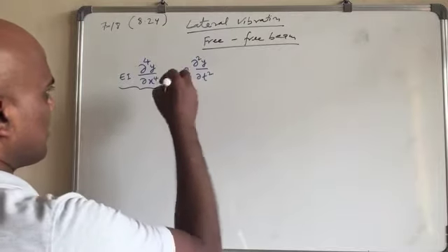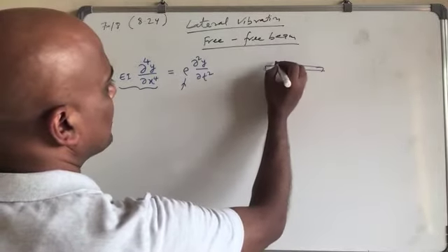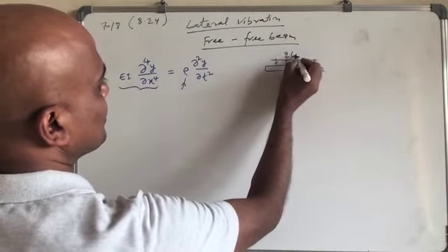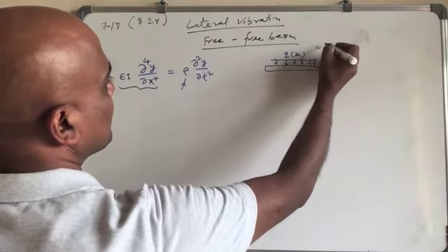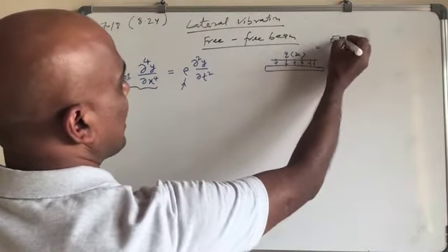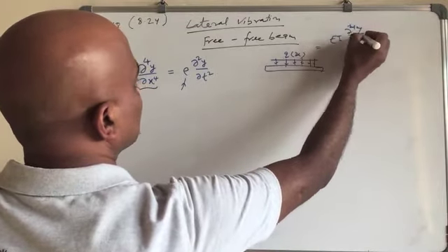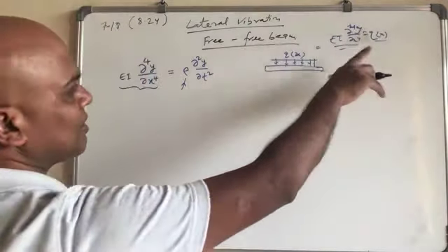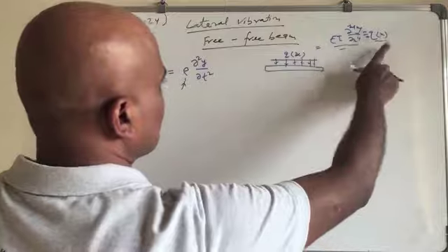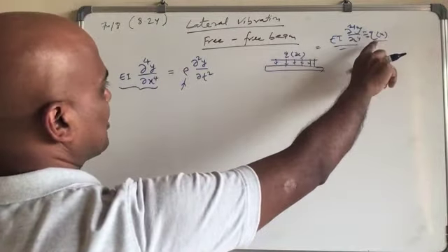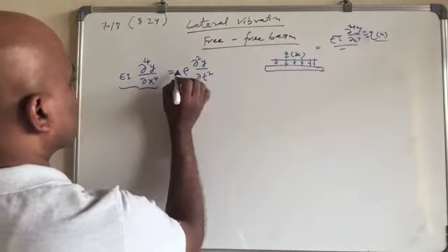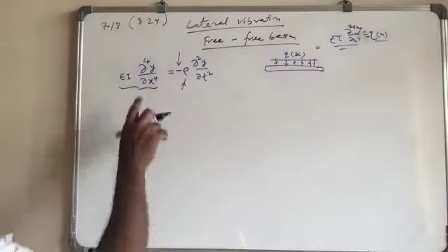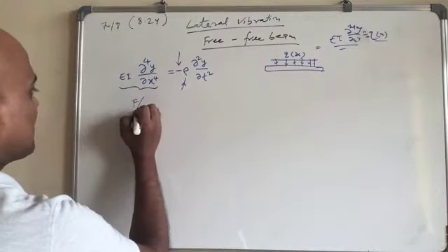So this represents basically the pressure. So this is a beam, and then remember from your solid mechanics, if you have a Qx, so Qx was given by this EI del 4y over del x4 was equal to Qx, right? So you remember. Okay, so this one actually is minus Q. If it is downwards, it should be minus Q. So in the equation you have a minus value here. So this is nothing but force per unit length.